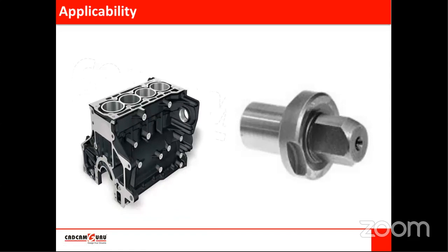These are the different conditions we have discussed. Engine block: the axis of this should be perpendicular to the surface, or here it is a locating pin. The axis of this cylindrical surface or circular part should be perpendicular to the bottom surface, meaning once it is inserted in a fixture plate, it should fit properly. There should be no change in orientation or tilt.